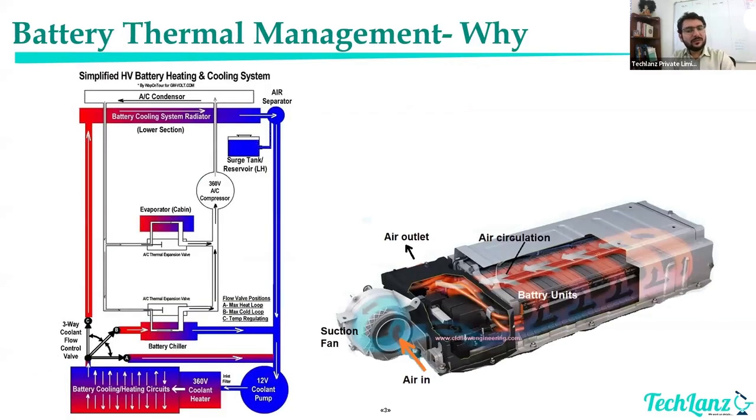First of all, you have seen that the thermal management system can become very complicated, right? For air cooling as well as liquid cooling. There are multiple components inside a liquid cooling system, be it evaporator, condenser, liquid cooling plates. Similarly, for air cooling, you have to take care of multiple things, like blower, PCM, and so on and so forth. But there are fundamental reasons you should understand for when to choose an air cooling system and under what conditions you should use the liquid cooling system, right?